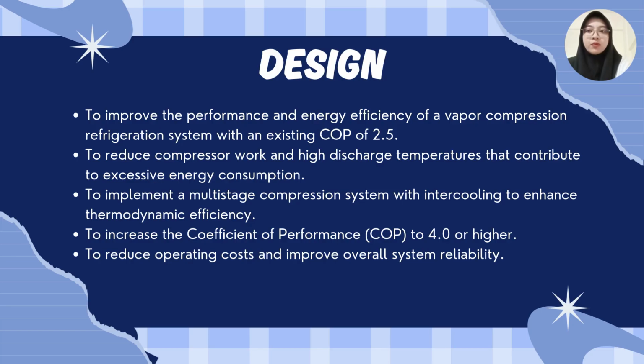One, to improve the performance and energy efficiency of a vapor compression refrigeration system with an existing COP of 2.5. Second, to reduce compressor work and high discharge temperature that contribute to excessive energy consumption. Three, to implement a multi-stage compression system with intercooling to enhance thermodynamic efficiency. Four, to increase the coefficient of performance COP to 4.0 or higher. Five, to reduce operating costs and improve overall system reliability.